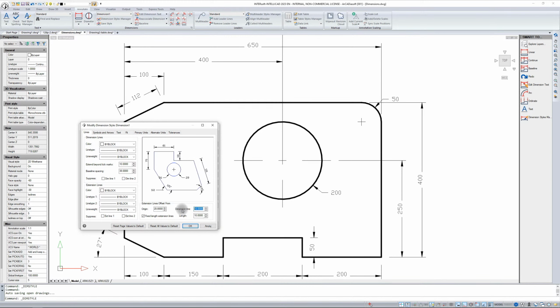So it may happen that for one drawing the size of the tick mark or arrowhead 10 will be good, but not for another one. So remember that you adapt it to the project and save it in the document and then transfer it between documents. Remember more or less what you did to make this style of dimensioning fit your drawing type.